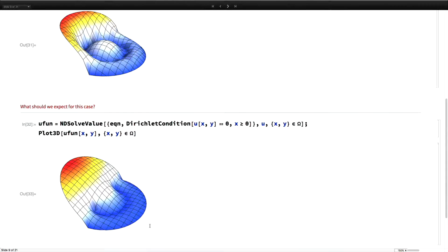This is what a finite element does. What it does is internally it recognizes that you explicitly told it in the domain that there is an internal boundary. I'm going to treat that as an internal boundary, and therefore that Dirichlet condition is going to get applied to that as well, right? So you need to be aware of what finite element is doing internally, so that you can get the right results.